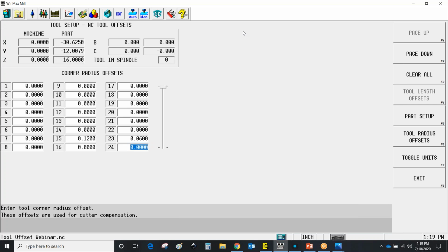So I'm going to open up here for questions. That kind of covers everything in how to use these offsets. I really don't have a whole lot more to add. There's just some controls there for turning things on and off that a lot of people aren't aware of, and we do get a lot of questions on that, especially how do I control the diameter on a tool that's called tool 500 or whatever. I have all my end mills set up as 500 series, and I need to be able to do that. So that's one way to control that.